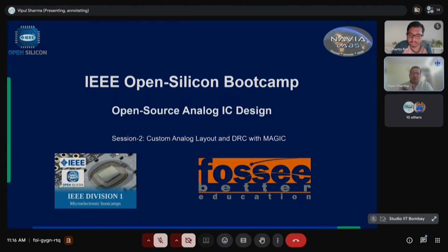Because we are right now starting to build, and maybe most of you are building, your first analog circuit, let us start with a very simple analog circuit, that is an op-amp. An op-amp is an operational amplifier, and it has some parameters. You start with some specifications like gain, bandwidth, slew rate, noise, PSRR, CMRR. All those are the characterization. So you have to characterize your circuit. First, decide the architecture, then characterize your circuit.